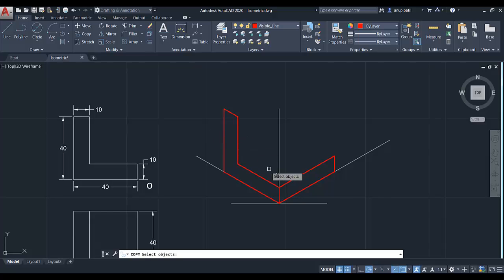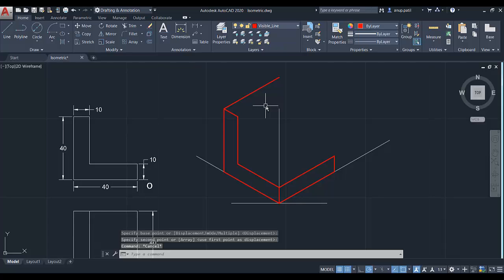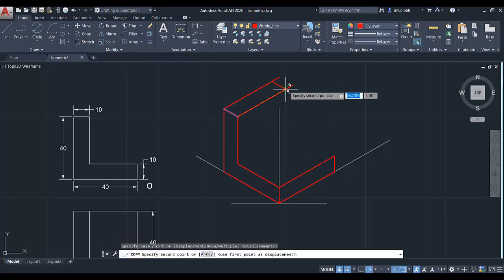With the copy command, or with the roller scale if you are drawing on the sheet, just draw the parallel line from these projections, then you can draw the line 40, then again a parallel line from this to this 40. So again draw with your roller scale parallel this line to this line. So this is completed, but the object is not completed yet.